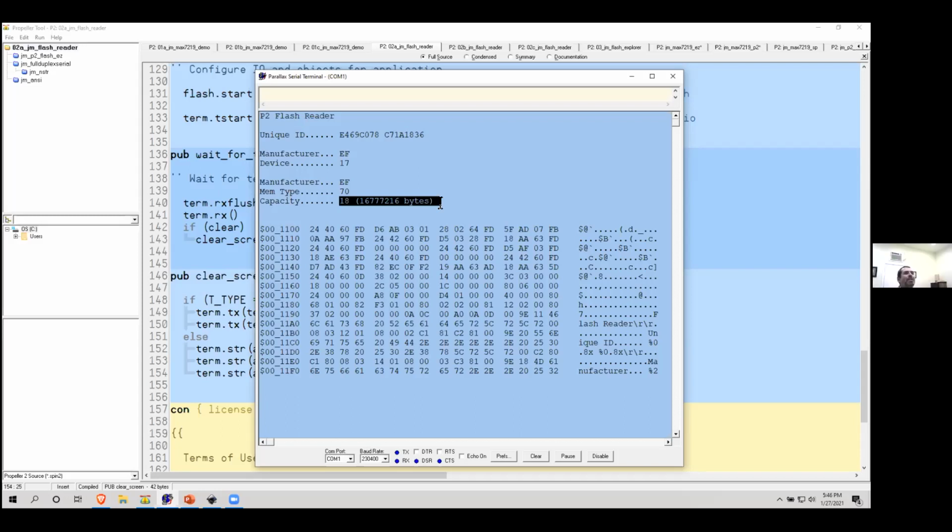Yeah, you just want to spread your write activity around evenly so that you're erasing and reprogramming everything at the same frequency. This is where journaling file systems come in, where you have this additive process where you keep rolling through the whole 16 megabytes, and you know where you can write a new record. So you write that record, cancel out the old one, and then periodically you have to do some erasures in order to free up some space.